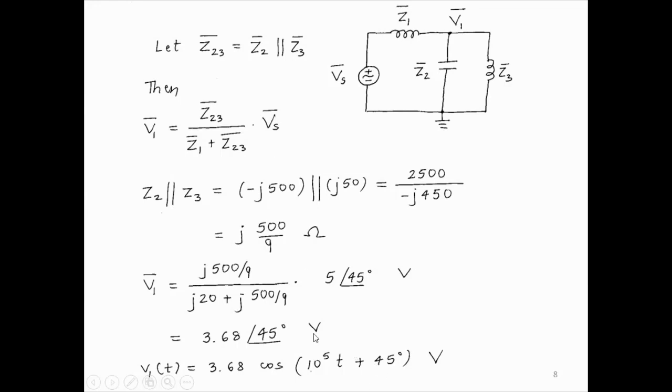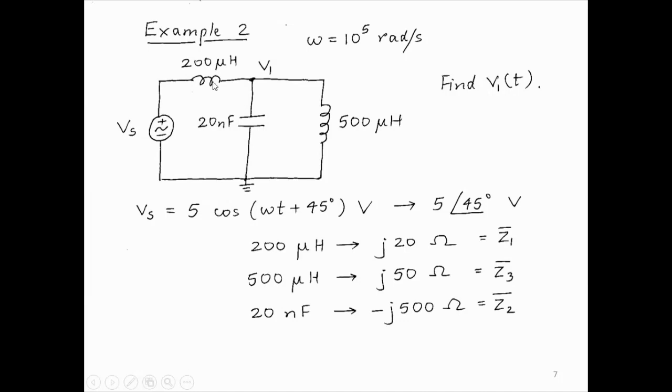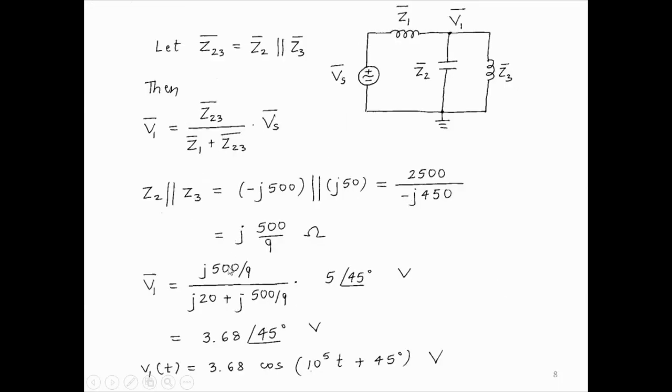The reason this happens is because all our impedances, all our elements, are either capacitors or inductors. All capacitors and inductors have a J here. There is no resistor, and so if there are only J elements in the circuit, then when we find any other voltage in the circuit, because all circuit elements have a J, through voltage division, parallel, series, everything, the J will stay as J, and eventually the J will cancel out. So any voltage will be some real number times the source voltage. And the real number of course will not change the phase of the original source voltage.